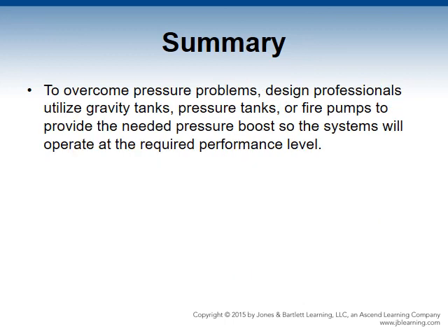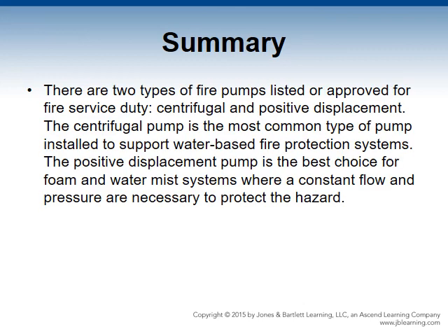To overcome pressure problems, design professionals utilize gravity tanks, pressure tanks, or fire pumps to provide the needed pressure boost so the system will operate at the required performance level. There are two types of fire pumps listed or approved for fire service duty: the centrifugal and positive displacement. The centrifugal pump is the most common type of pump installed to support water-based fire protection systems. The positive displacement pump is the best choice for foam and water mist systems where a constant flow and pressure are necessary to protect the hazard.